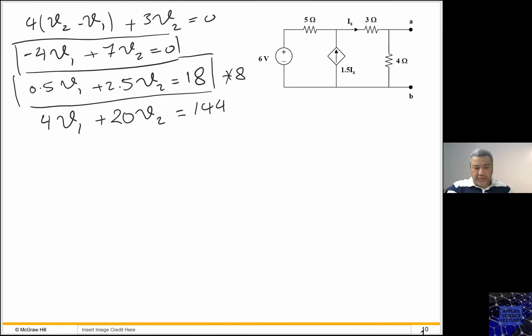Again, you can solve it the way you want. Here in our dependent sources, we only have one extra relationship between our controlling variable and our standard variables. Once you substitute it, you reduce the number of the variables, becomes back to, here in our case, two variables. So you have two equations, two unknowns.